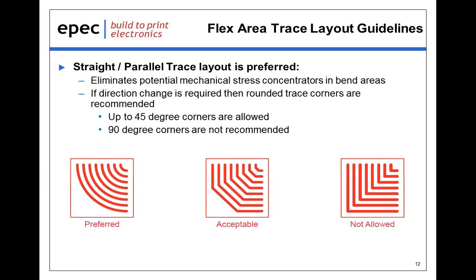Another significant element is the configuration of the traces in the flex area. The standard recommendation is that the traces be run in a straight line from one rigid area to another, parallel to one another, without any changes in direction, if at all possible. And by doing so, you eliminate any potential mechanical stress concentrators that would be created in these bend areas.